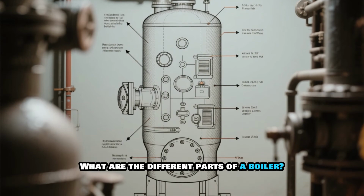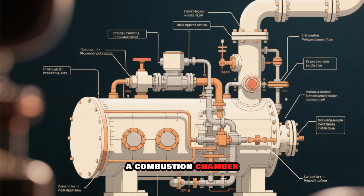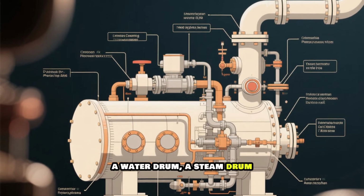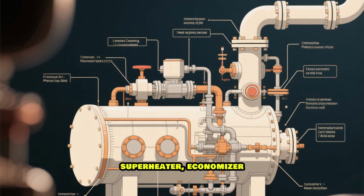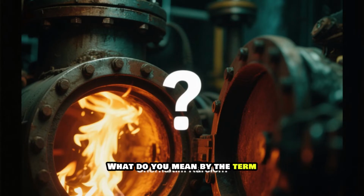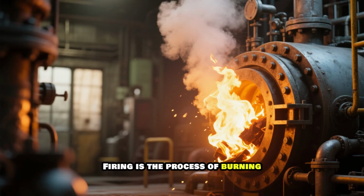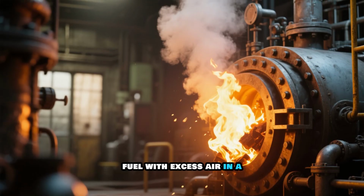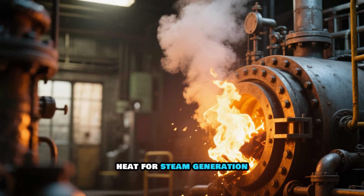What are the different parts of a boiler? The main parts of a boiler are a furnace, a combustion chamber, a water drum, a steam drum, superheater, economizer, air preheater, and an ID fan. What do you mean by the term firing in a boiler? Firing is the process of burning fuel with excess air in a boiler to produce heat for steam generation.